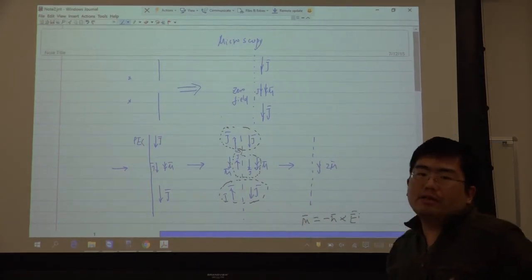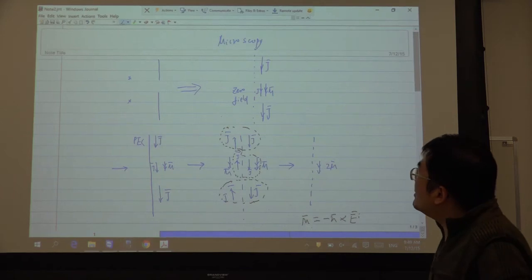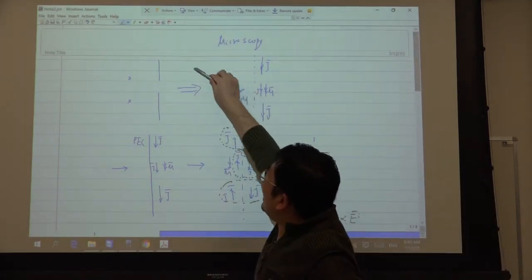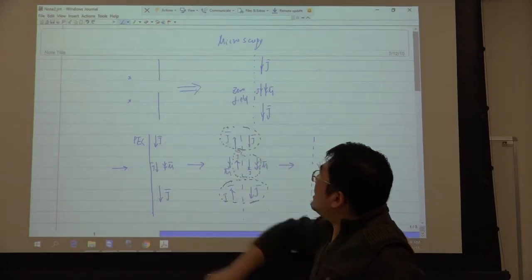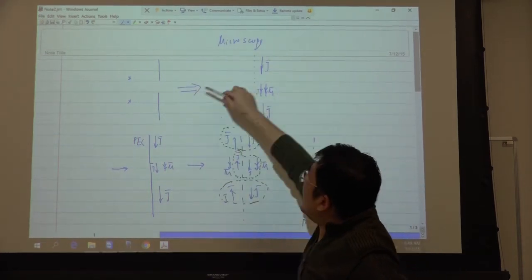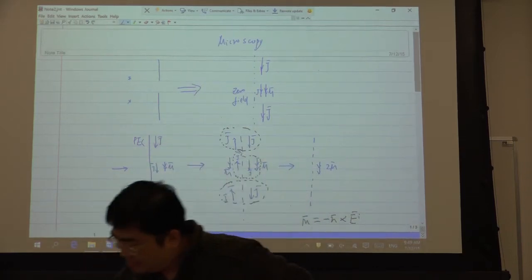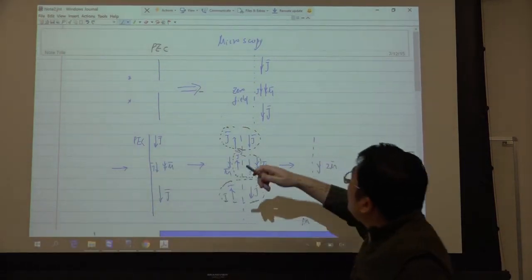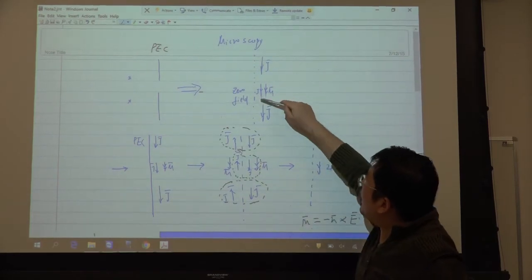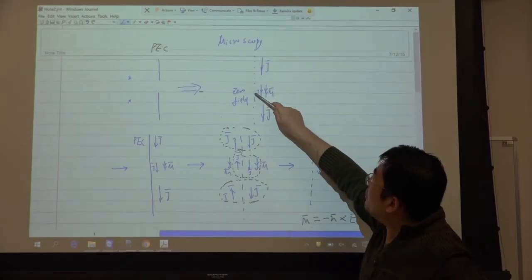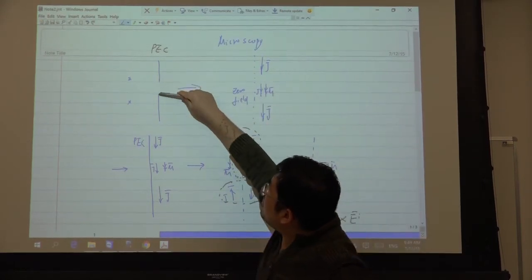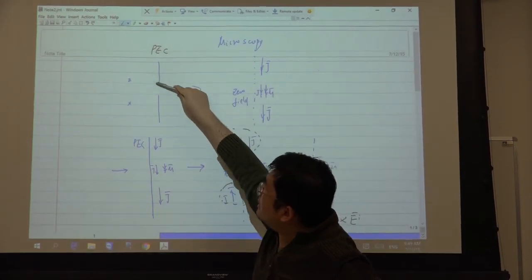According to the equivalence principle, the field behind the screen can be represented by the equivalent current at this PEC plane. We are assuming that the screen is PEC. There is an equivalent electric current and magnetic current at this aperture, because this aperture is air.